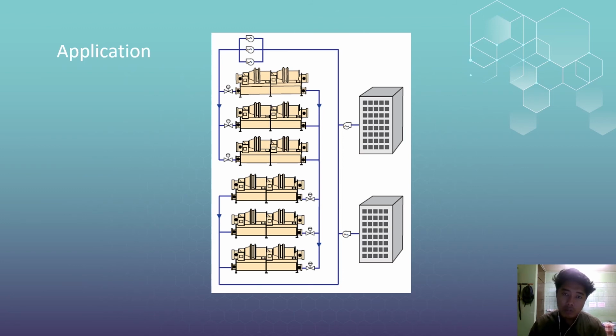Alternative fuels for some or all of the chiller may be attractive. To minimize power, large systems must be very efficient. The upside of a large system is the amplification of energy saving. A relatively small percentage of energy saved becomes more valuable. For this reason, highly efficient series counterflow arrangement is popular for large systems.